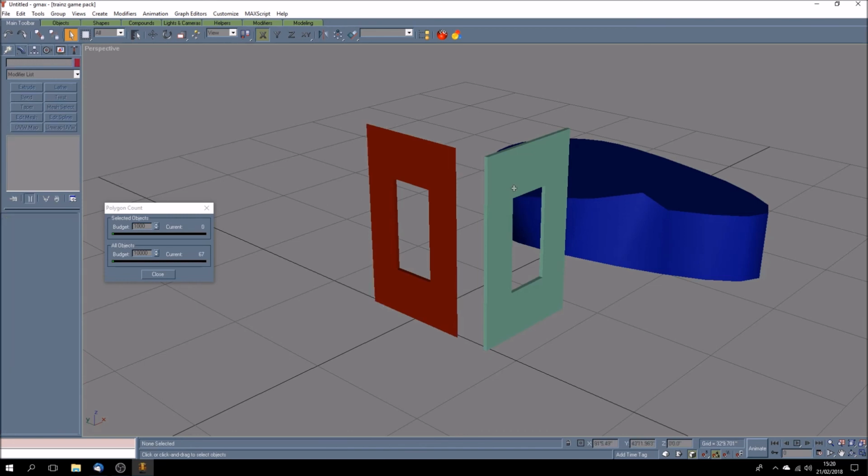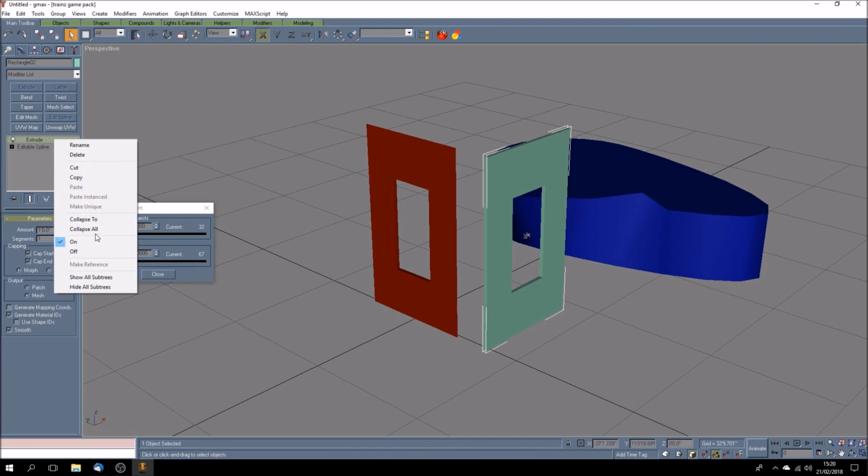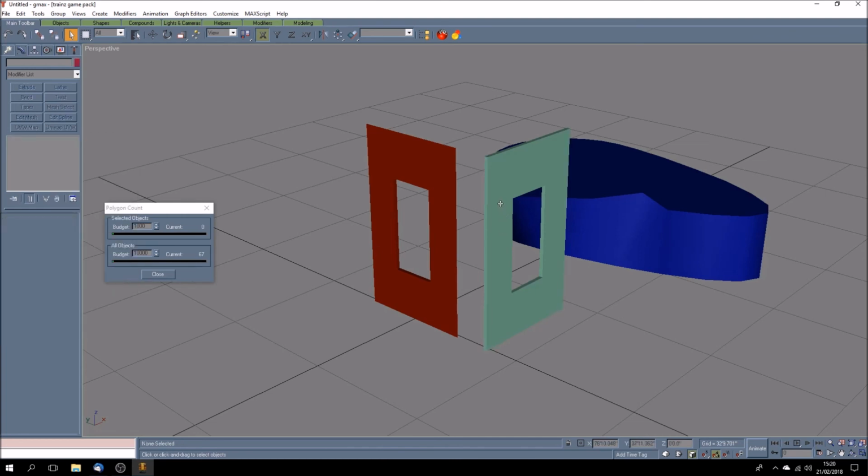To go over here, don't we? Which has got 32. So first of all, we need to reduce that one down to an editable poly, we're going to use our collapse business, and then we're going to edit it, take out the unnecessary polys, and get something less than 1/6 the size, which is always good news in Trainz. And knowing which polygons you can delete is half the battle. Knowing what is going to overlap will become pretty obvious. So use polys with economy.